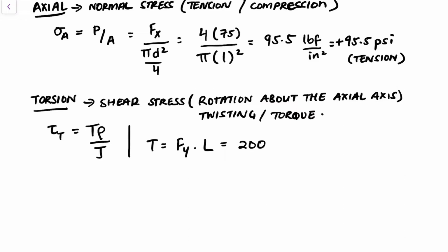At least for the purposes of this class, I wouldn't worry about signs when it comes to shear stresses. Just for the sake of this class, because if you try to take the signs into consideration, you'll be working with tensors and that makes the problem really complicated. And from a design perspective, you don't really need to know the signs of the shear stress, because especially when you're dealing with drive shafts that are really long, the transverse shear isn't really that important, so you don't need to add or subtract it.